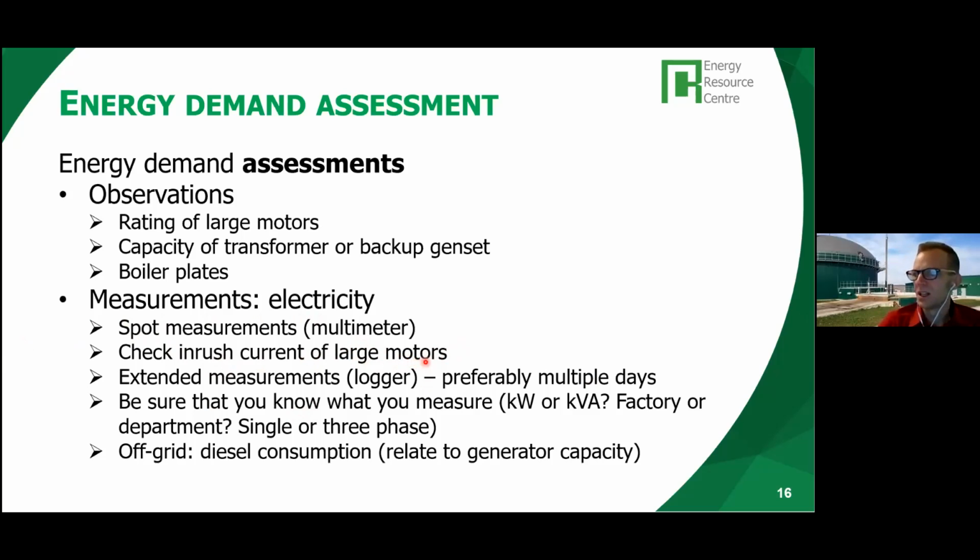If you have a power logger, so one that can take measurements, for example, every second, and store them, measurements of current and voltages, and log those over a longer period of time, then that can give you a very accurate indication of the overall consumption and peak loads of your factory.